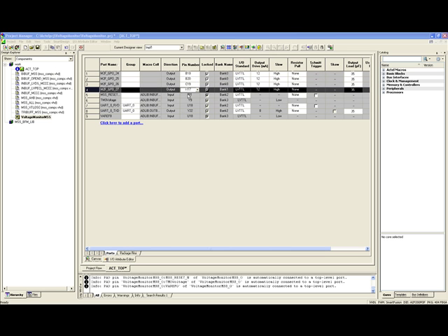These pins directly drive LEDs 1 through 4 on the SmartFusion evaluation kit board. Note that you can change many other I/O attributes on this page, such as I/O standard, slew rate, resistor pull, and output load. MSS pin assignments are locked, but you can edit some MSS I/O attributes in this view.